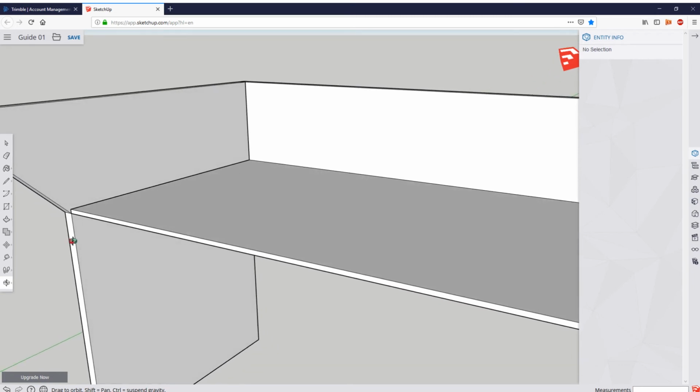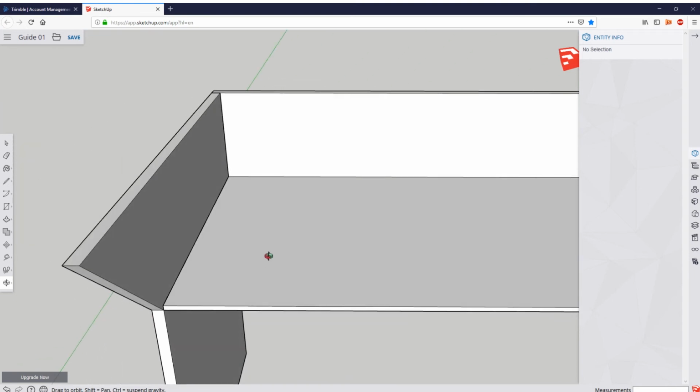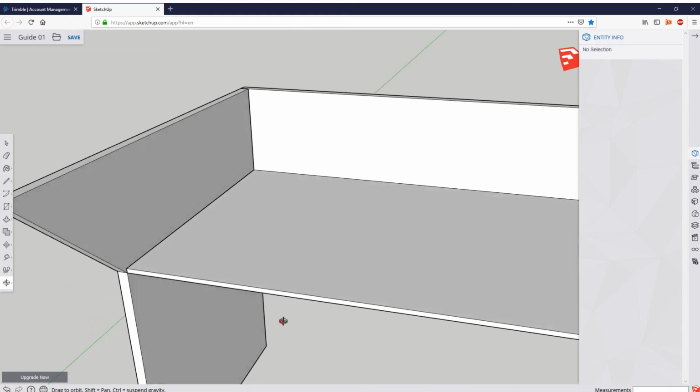Now, obviously, you would need to do a joint here that would go like this to make the front. Now, again, if you possibly can have a metal plate shaped like this, I would do the metal plate, and then fasten it here to an actual wood panel, so that the whole thing doesn't need to be metal, but it's a lot easier if you can do at least this angle bit in metal, and it's also a lot easier to shape, and if you make a mistake with bending it, it's somewhat easier to fix than a mistake with wood, because metal is very bendy in small sheets like that.